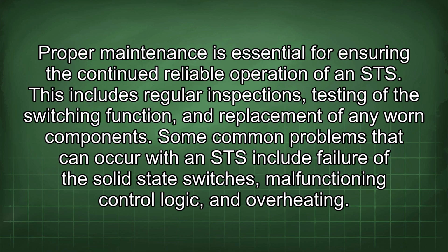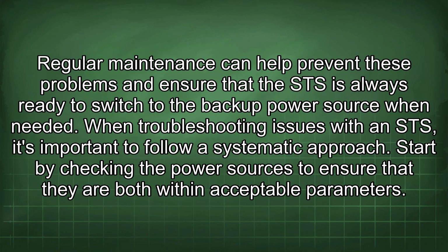Proper maintenance is essential for ensuring the continued reliable operation of an STS. This includes regular inspections, testing of the switching function, and replacement of any worn components. Some common problems that can occur with an STS include failure of the solid-state switches, malfunctioning control logic, and overheating. Regular maintenance can help prevent these problems and ensure that the STS is always ready to switch to the backup